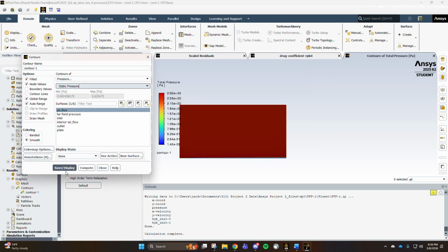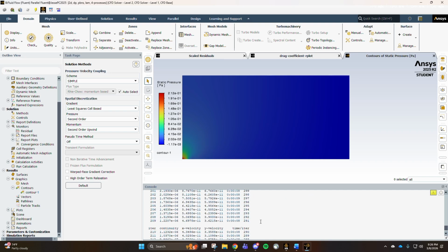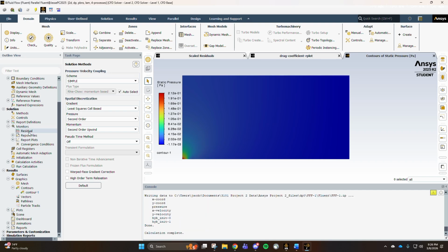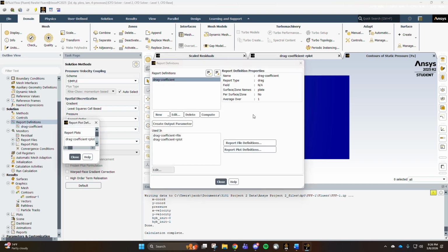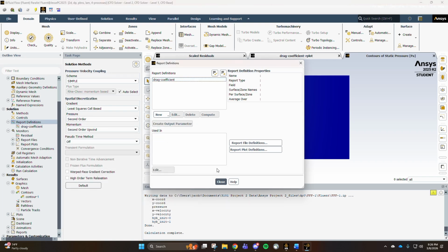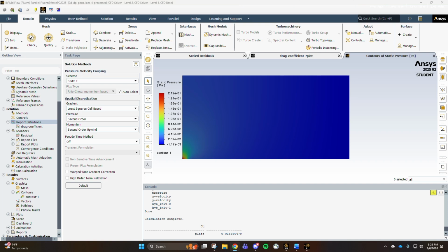And if we go to static pressure, this is what we are given, because it's from the frontier where there's somewhat stagnation where the velocity hits. But that's how it looks for the contours, and again, the drag coefficient is the same, but we will report it again just for good measure. Yep, 0.0158, perfect. And those are the contours, and now we're going to go into the post-CFD, and we're going to do the velocity profiles and the wall shear stress and skin friction coefficient graphs.